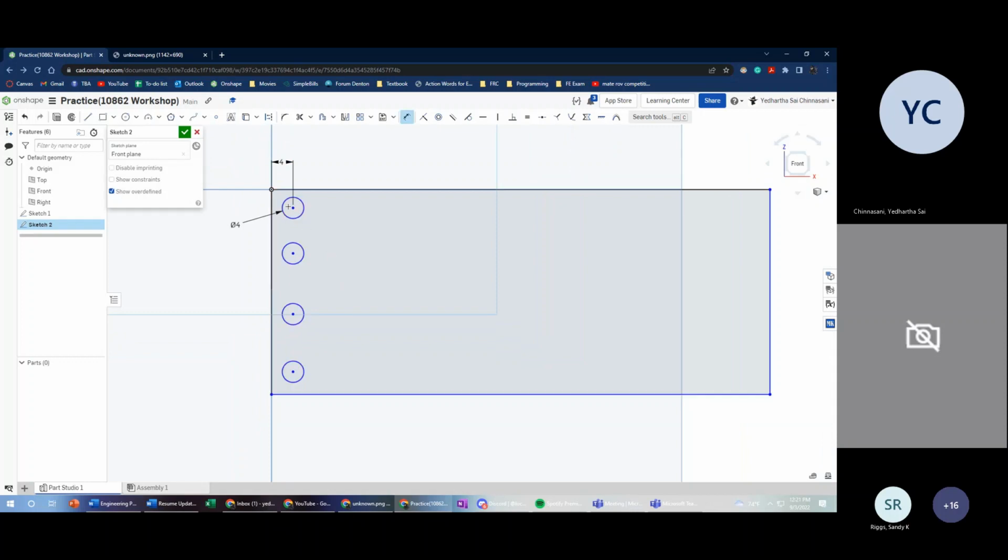So that's basically it. And then for this, you can't do anything about it. So I'm just gonna do a millimeter. Here to here. Something other thing you guys have noticed is that whenever you have a random circle out in the middle of nowhere, it's blue, right? And you see some of these lines are blue and some of these lines are black. Whenever you see that, whatever you see in black is defined. The software knows that there's a value that exists for that line, for that circle, right? It knows where the circle is on the document.